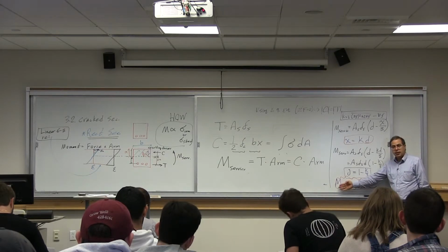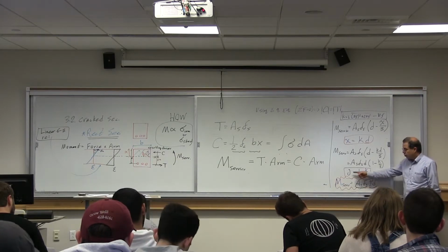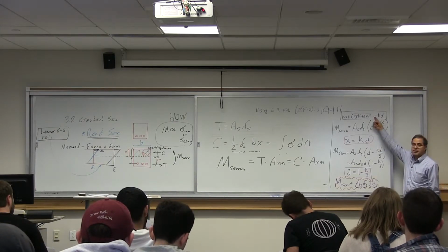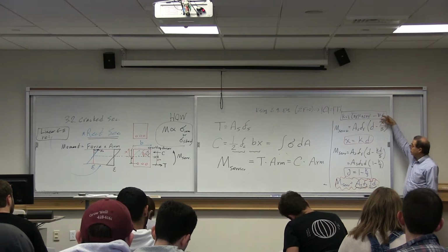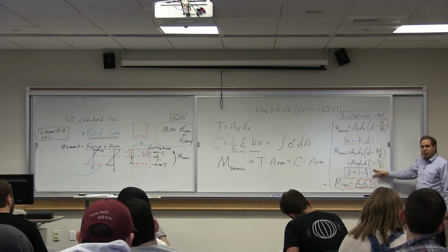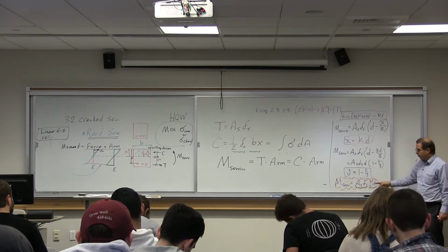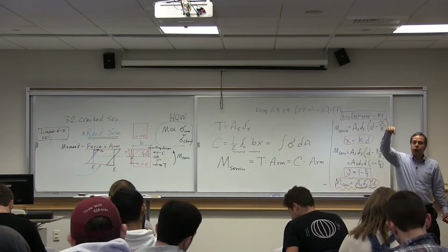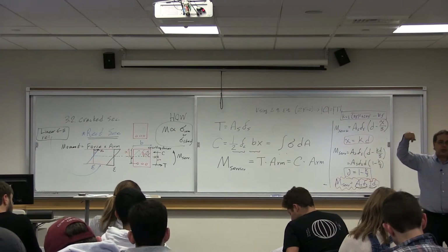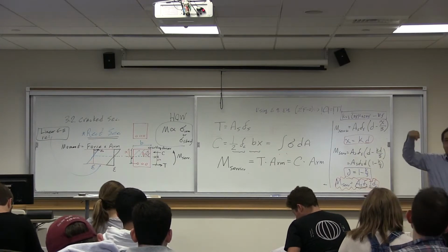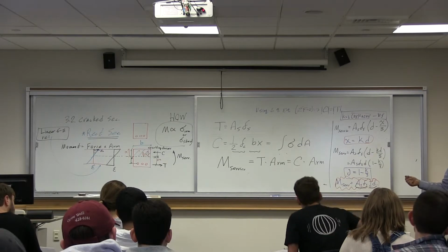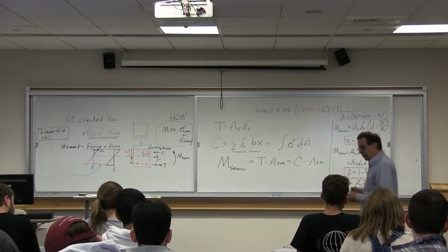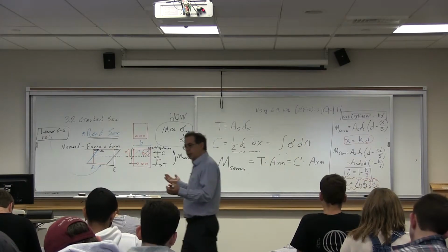That's the moment. Where do I get j from? j is 1 minus k over 3. Where do I get k from? k is this. You calculate k, you calculate j, you find this relationship, you find the M service. If you have M service, given the load applied, you say, don't let a truck more than 25 kips pass this bridge. So that's a practical application when you want to rate a bridge.